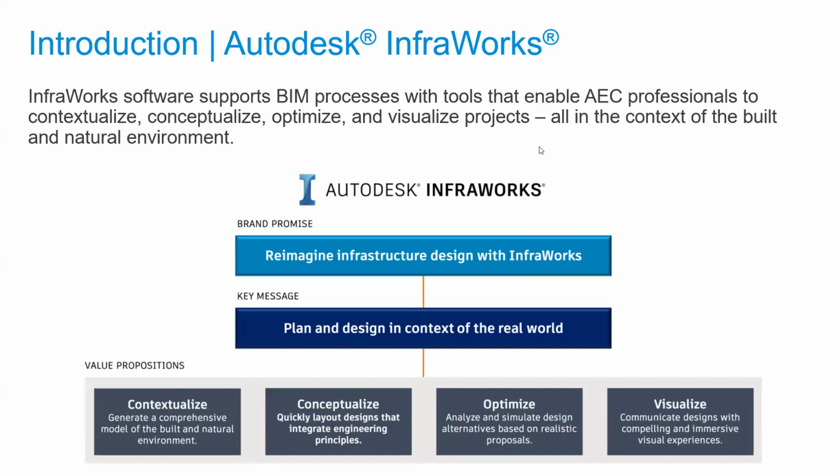Once the project is approved or you get some funds, you can do surveying, either using a drone to collect the data for photogrammetry, or you can use ArcGIS to update that infrastructure model that you have created within Infraworks, to ensure that you are using up-to-date imagery. So it's not recommended to use the Bing map within Infraworks at the detailed design level.